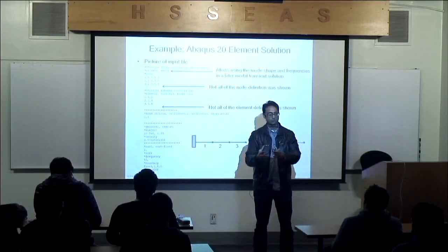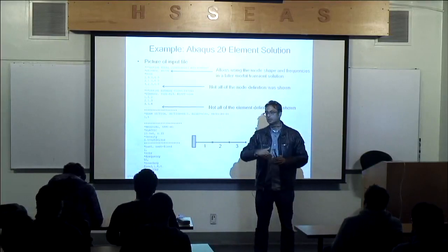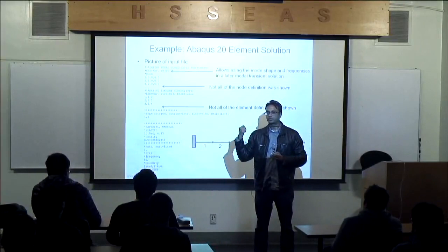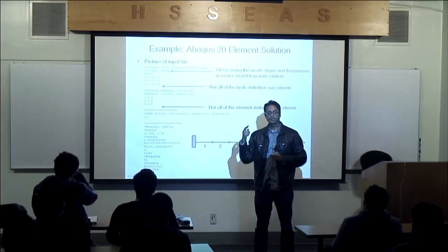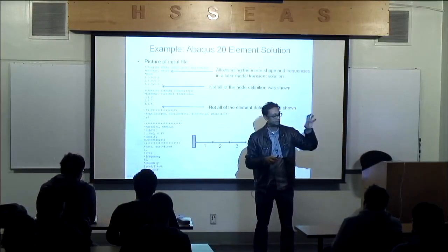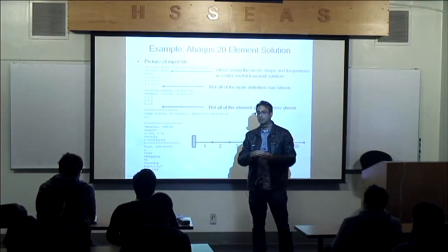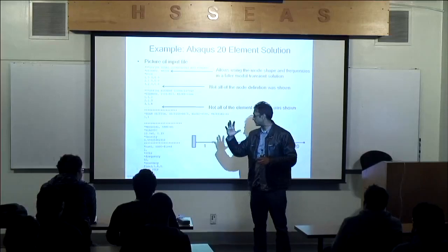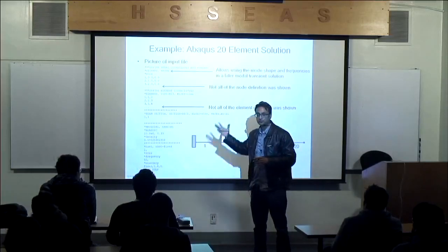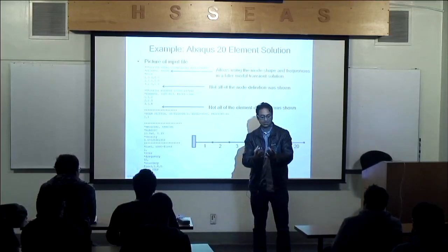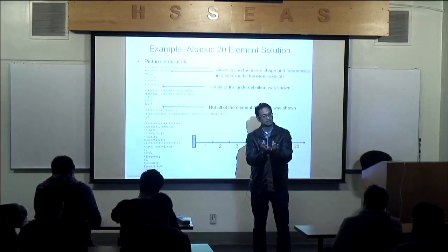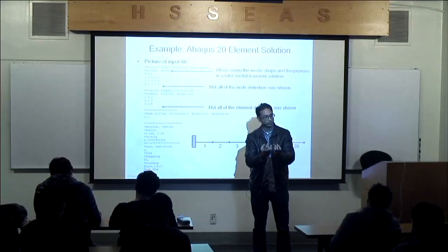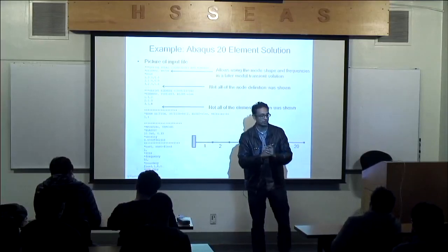If you need to do some random vibration analysis or some transient modal solution, guess where I will go? Do I have to run this again and wait for a couple hours? No. I just did it once, and that's where I'll go. That's my database. I see this frequency analysis, this free vibration problem, as a DNA. It defines how that structure is going to behave in its lifetime. It has all the information on how that structure is going to behave. That's the way I view it.